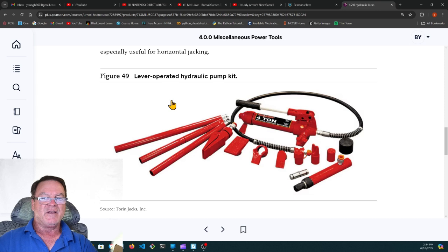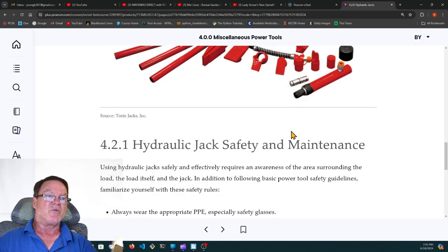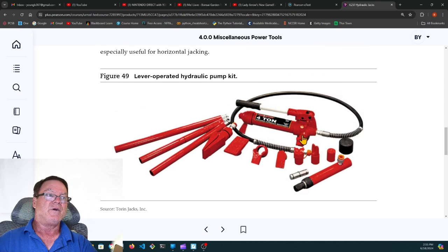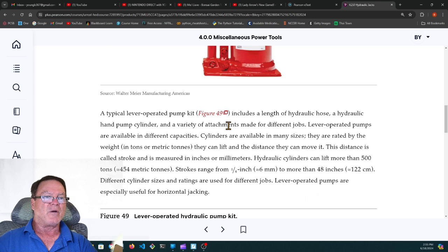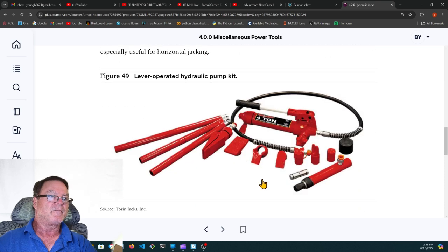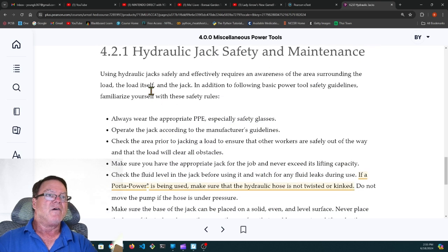And they have cups that are different sizes, and you match up the cup with the blade, and then as you pump the handle, the teeth or the blade will go through the side of the panel, and it'll pop out a nice, smooth, round hole. So electricians use this kind of a porta power, I think they call it. Okay.